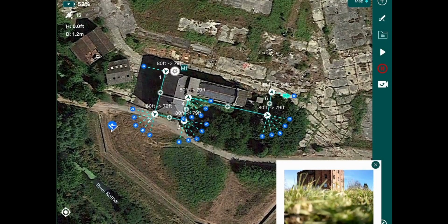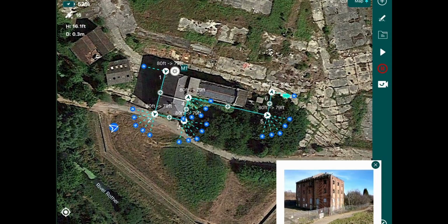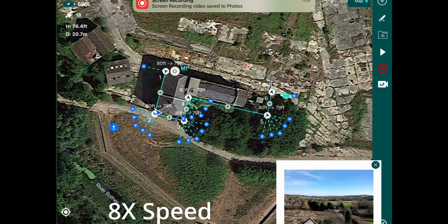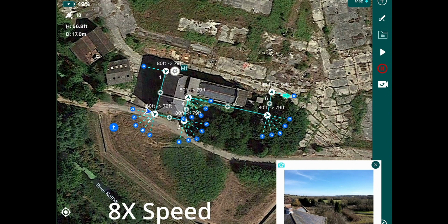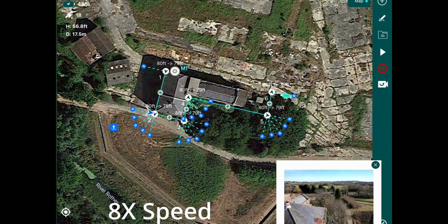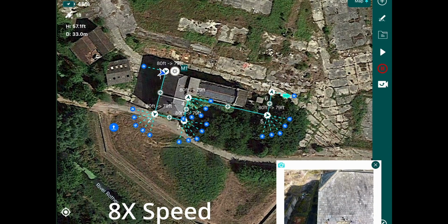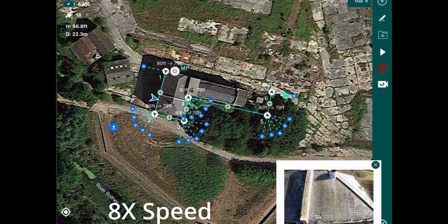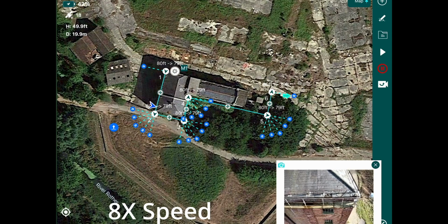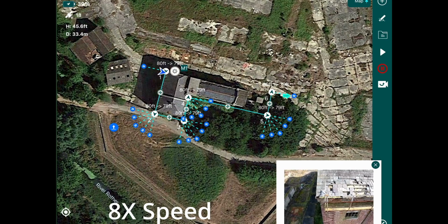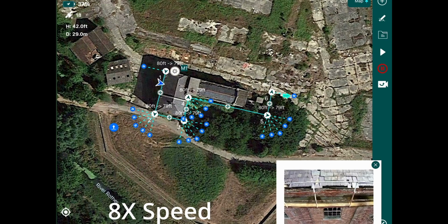So in the second part of the video we are capturing our facade, and we're doing this manually. So just taking off, getting to a good height. We've sped this up as well to quicken the process. Go along, set the gimbal tilt. And this creates a kind of wrapped effect over the end of the facade. So when it comes to processing, we can match both the Nadir and the facade together.